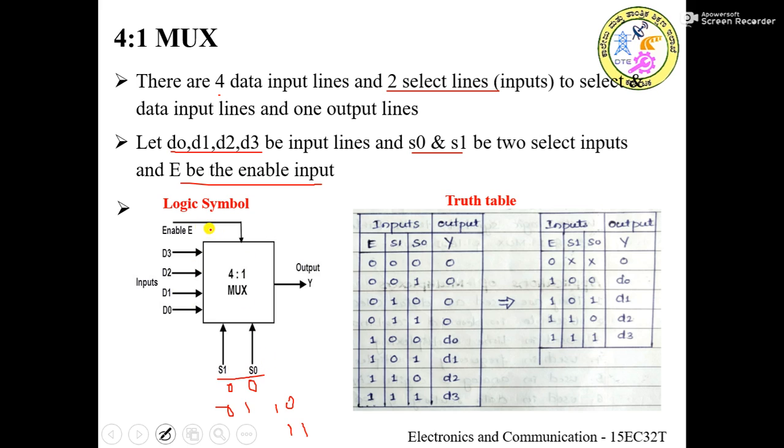So as we discussed about the enable signal, this is an active high signal. So this should always be set to 1. If it is set to 0, then this total system itself will be disabled and output will remain always 0 irrespective of the content of select line. So let us assume that it is connected to VCC or it is connected to 1 and the system is enabled now. Once the system is enabled, the system will look for the content on the select lines.